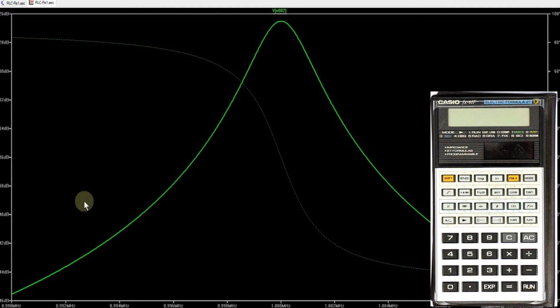Now, as you can always see in LTspice here on the lower left, the dB values, the phase, and the frequency are displayed. And we have a peak amplitude of minus 26.5 dB. So if we go 3 dB lower, that would be minus 29.5. That is around here.